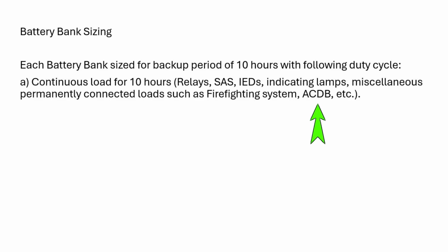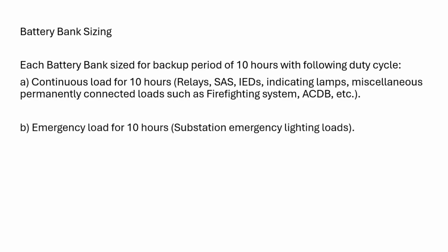Next, we consider the emergency load, which refers to the emergency lighting load. In the event of a total blackout during nighttime, all emergency DC lights will turn on. We consider this extreme condition to calculate the maximum lighting load consumed during 10 hours for the emergency lighting purpose.